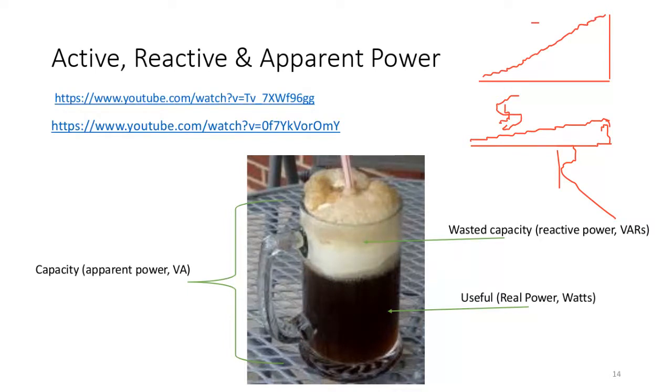So to supply the same real power, you need to push more power, because you have this reactive power. Same real power, but you need more power to supply because of this presence here. So we wish to have real power equal to S. We wish to be like this: unity power factor.